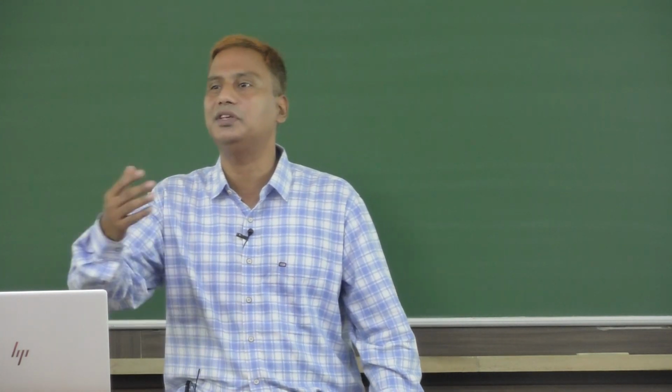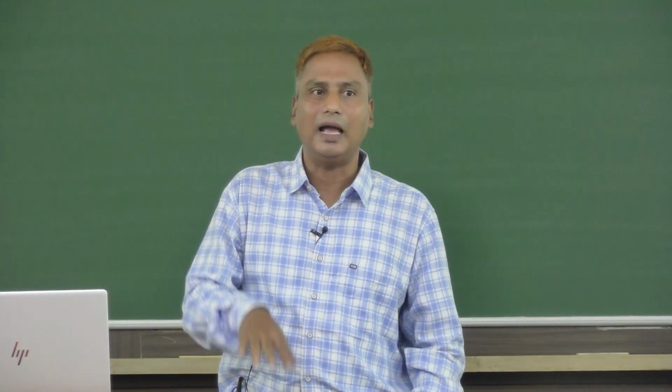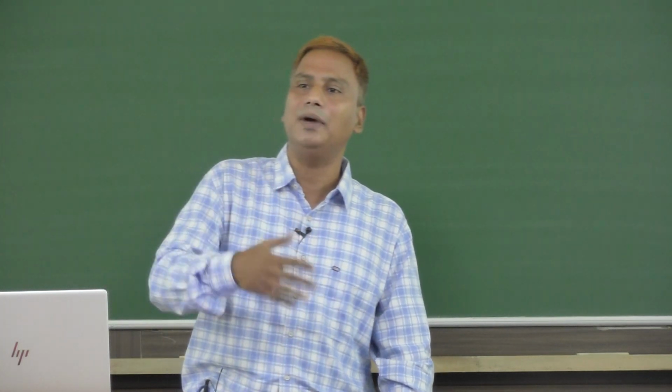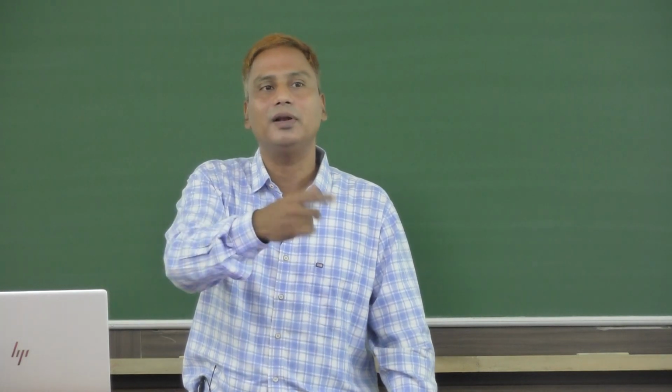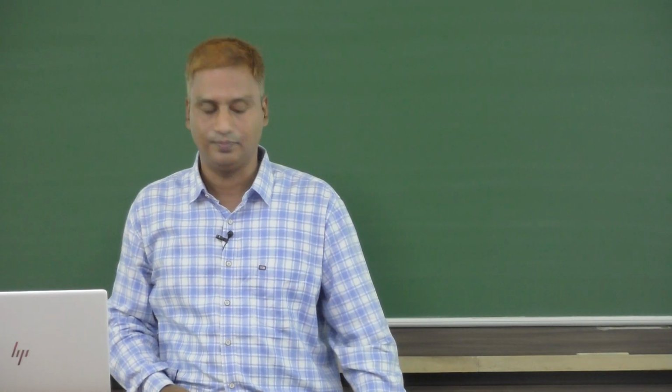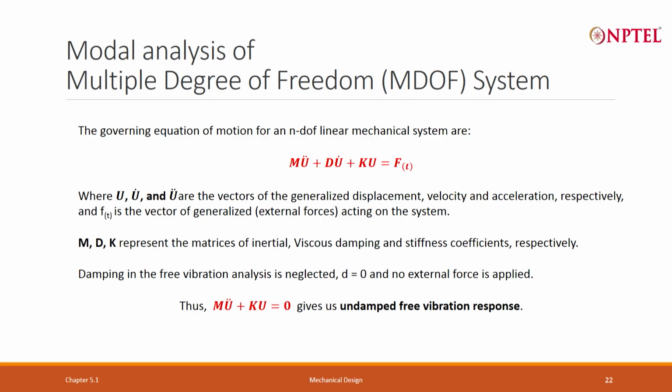So, what we do, basically, we check the road loads, we put the instrumentation, we see all the amplitudes, we record, then we come back, we analyze, and then we put either in simulation or experiment what are the things that failed during that time. The transient is a time varying response, but again sinusoidal, but time varying, amplitude or frequency or both can keep on changing, but we know how it is changing, that we know. In random we do not know.